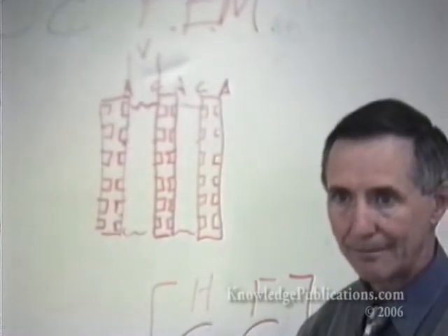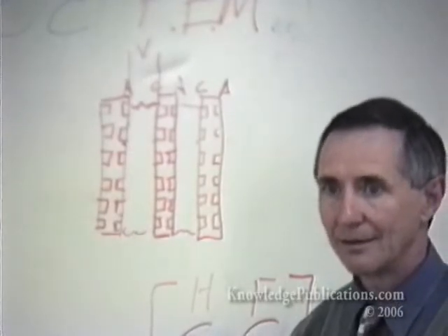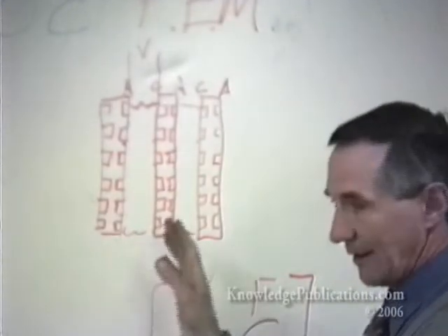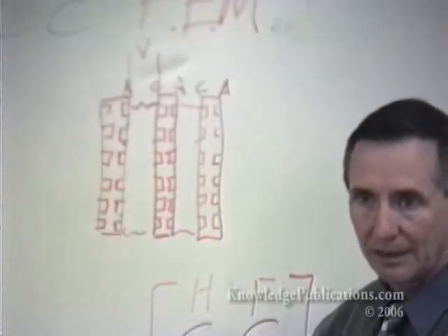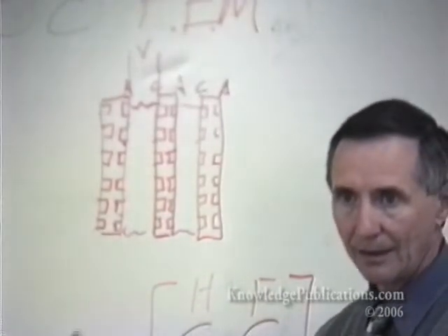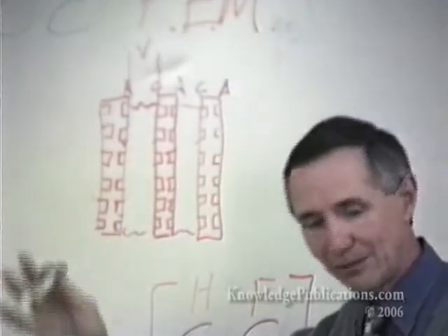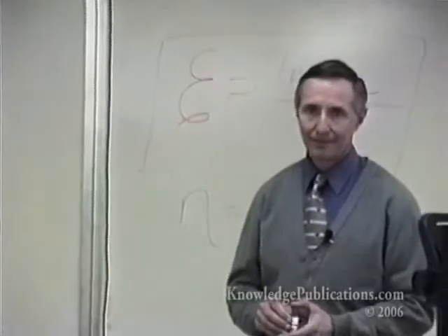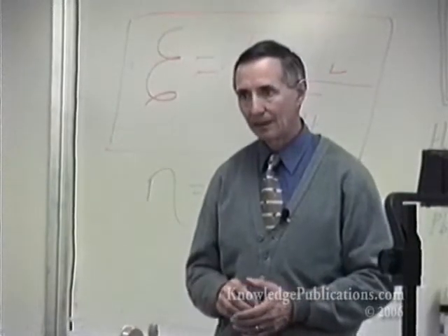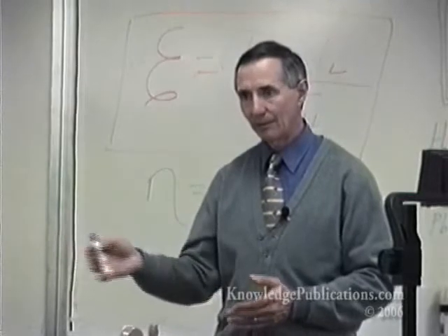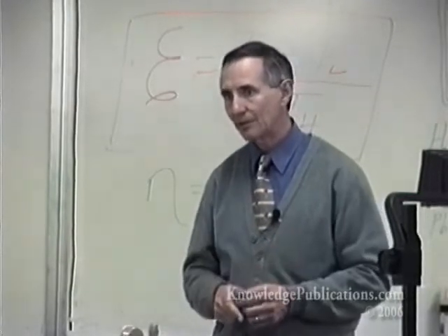Now, what about the electrolyte? How do you store your electrolyte? Well, this electrolyte needs to be stored in a humidity-controlled system if you're using PEM. Well, I was thinking of the phosphoric. Oh, phosphoric acid. Well, you can just get phosphoric acid that's pretty pure from the manufacturer, and store it without contaminating it with oil or other things that are common to storage.